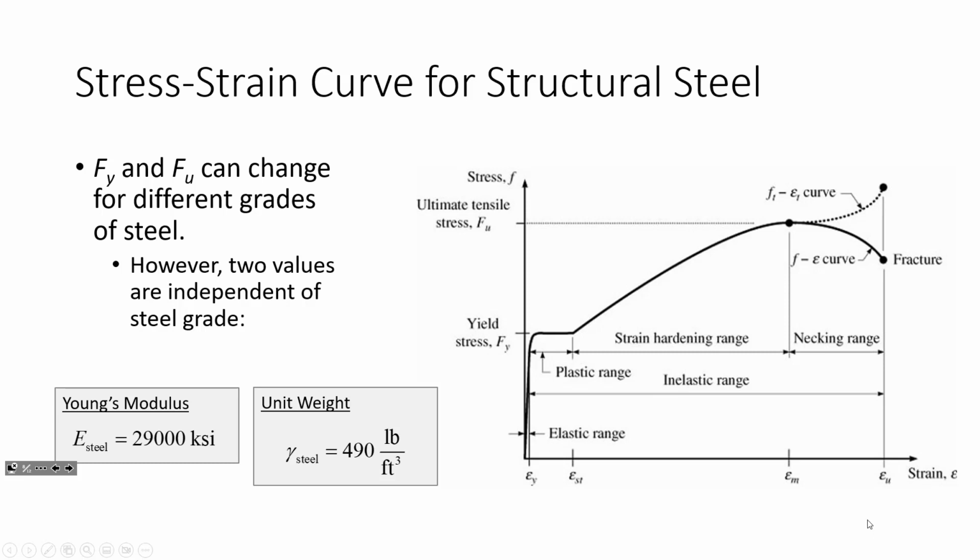So for example, when we are designing in earthquake-prone regions, we have to design structures such that they have a significant amount of ductility, because when an earthquake rocks a building, that sucker wants to fall down. So if we can withstand a lot of that energy and absorb a lot of that energy through inelastic deformations, that's great. So steel's really good about that.